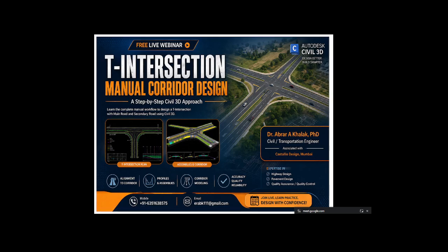So the objective of this session is not just to teach you which button to click in the software, but my goal is to help you understand the complete engineering workflow behind a real intersection, from alignment and profile creation to assemblies, corridor regions, and the final corridor model. By the end of this webinar, you will understand why multiple assemblies are required, how corridors transition at an intersection, and how to build everything manually without relying on the automatic intersection tools.